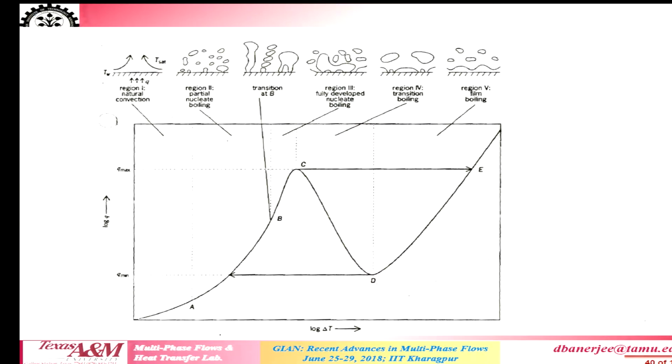Number two, those temperature fluctuations are actually of smaller size than your typical thermocouple. Your typical thermocouple is of the order of a millimeter, whereas the vapor bubble that forms in a refrigerant, for example, is of the order of about 600 microns or 0.6 millimeter. So these temperature fluctuations that you are seeing occur in the range of about 300 to 500 microns, about 0.3 to 0.5 millimeter.